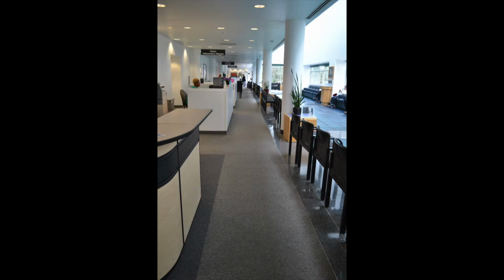Wheelchair passing width is 5 feet. Considering that these service desks may have people in front of them, this aisleway is too narrow for wheelchair users or people using a cane.